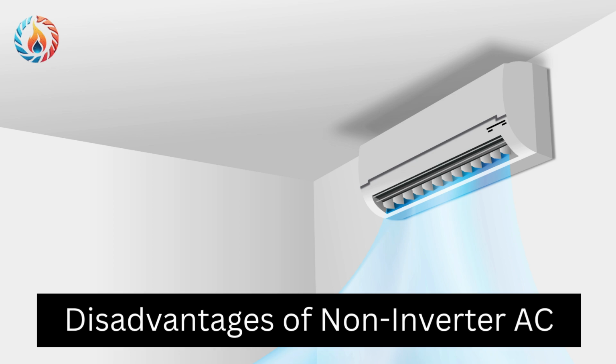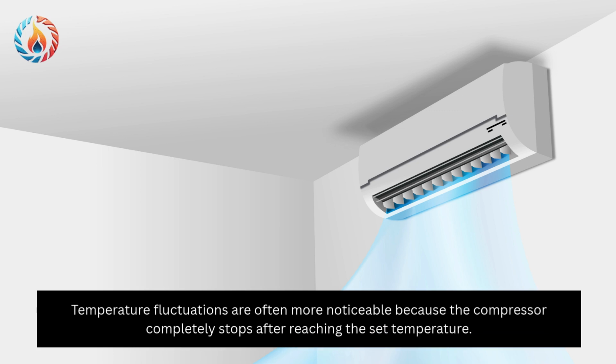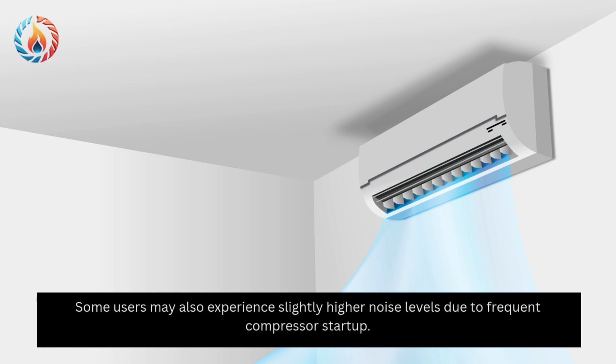Disadvantages of non-inverter AC. The repeated on and off operation may result in higher electricity consumption during extended use. Temperature fluctuations are often more noticeable because the compressor completely stops after reaching the set temperature. Some users may also experience slightly higher noise levels due to frequent compressor startup.